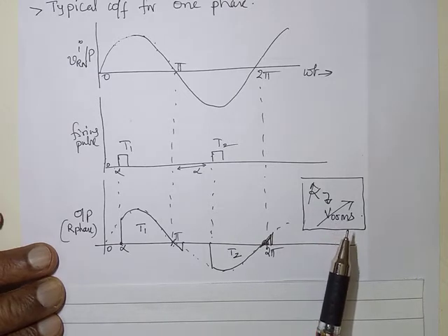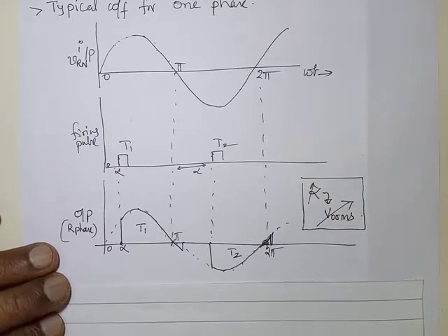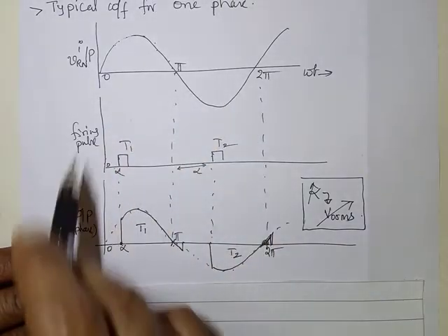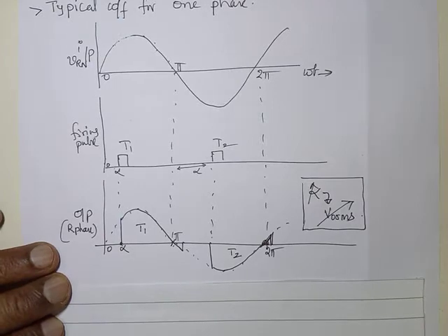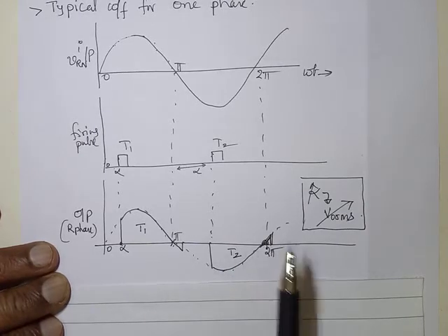Basic principle of chopper, AC chopper. So now this is done even for the other two phases also. As a result, the effective voltage given to the induction motor will change. Something that would have happened if we would have used a transformer, the same thing happens here.